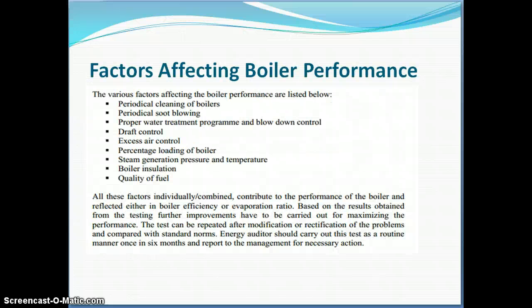Let's quickly see some of the factors which affect boiler performance. If dust and dirt deposit in the boiler, and sometimes the hardness of the water creates problems of deposits, these need periodic cleaning. This can affect the boiler performance as far as heating is concerned. Periodical soot blowing, a proper water treatment program, blowdown control, draft control, excess air control, percentage loading of the boiler, steam generation, pressure and temperature, boiler insulation, quality of steam, and quality of fuel. All these are factors which, if not considered properly, may lead to poor performance of the boiler.